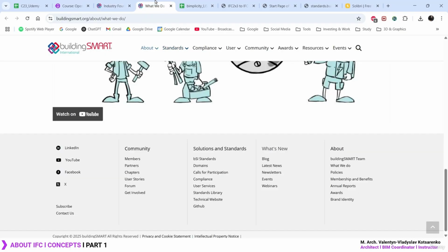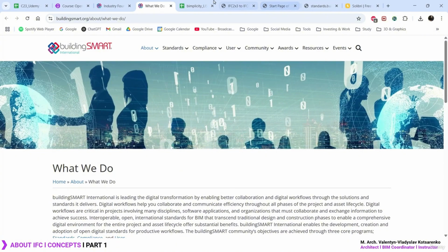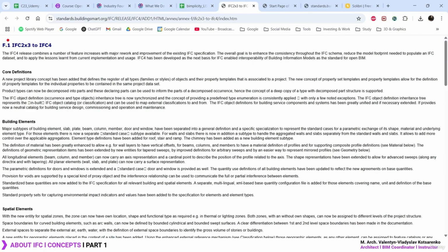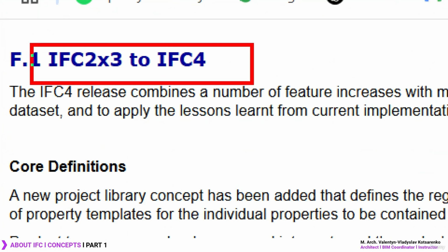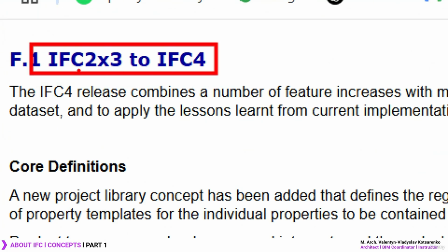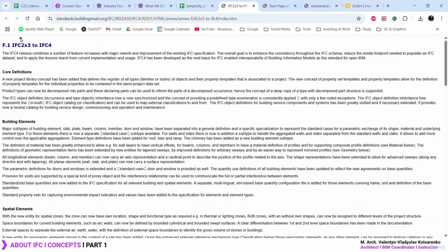best idea. Now, you can also notice, for example, in SketchUp, we had two different formats. The same happens in Revit and ArchiCAD. We get two different IFC formats. For now, we got IFC 2x3 and IFC 4. To give you a general idea of the difference between each format, IFC 2x3 is going to be the most adopted one, because this one has even more time in the market. It's much more likely that this is a format that is always going to be available in pretty much all types of BIM software or BIM tools, okay?